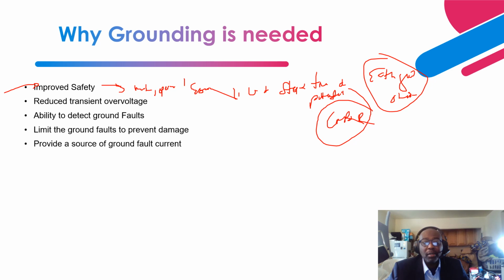It's based on a lot of parameters that are input into the simulation software to determine that the ground potential rise meets the required criteria to prevent shock hazards that can be encountered based on step and touch potential.